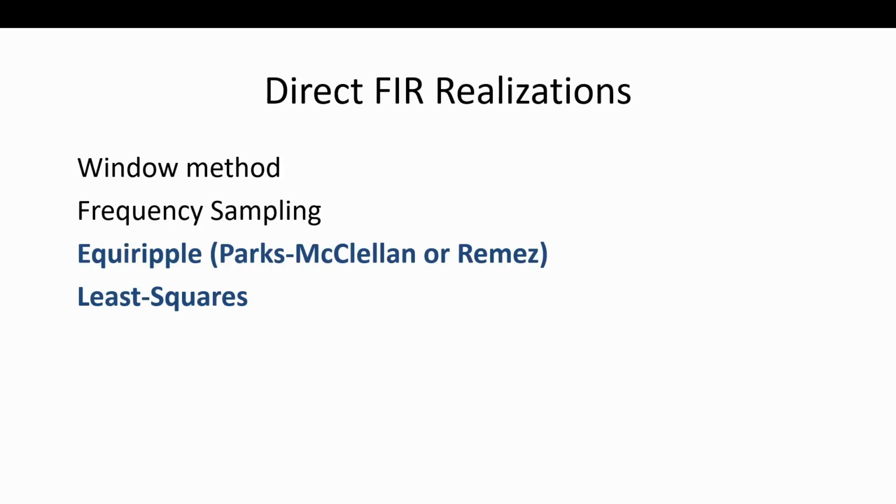Okay, so now, how are we doing? Equiripple and least squares. These two approaches are the optimum filter design approaches. In fact, I'll tell you right now, least squares is my go-to. When I need a filter, I go to least squares, especially for wireless comm, where we're interested in RMS error, things like EVM, not peak error. So that's the difference between these two. But let's talk about them.